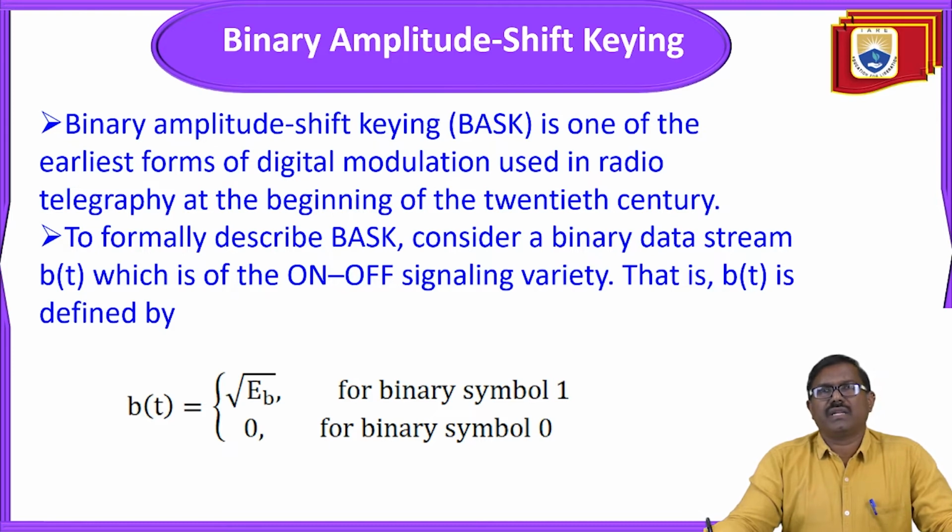Now the BASK. Binary amplitude shift keying is one of the earliest forms of digital modulation techniques used in radio telegraphy at the beginning of the 20th century. So this is the basic one, or the starting one. To formally describe ASK, consider a binary data stream b(t) of the on-off signaling variety.